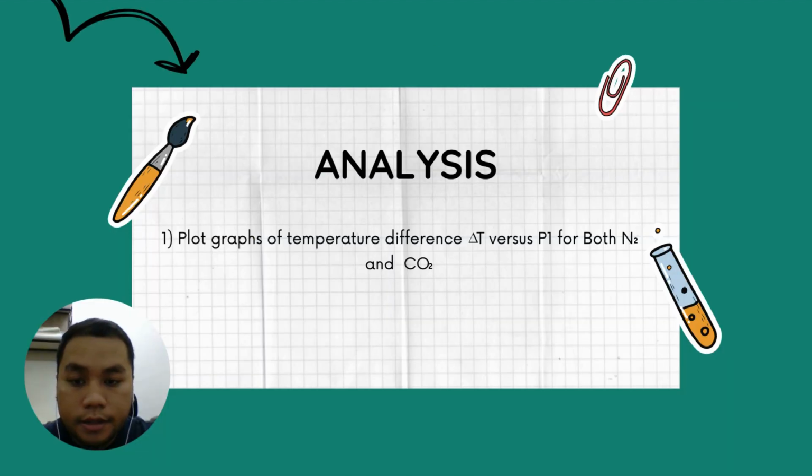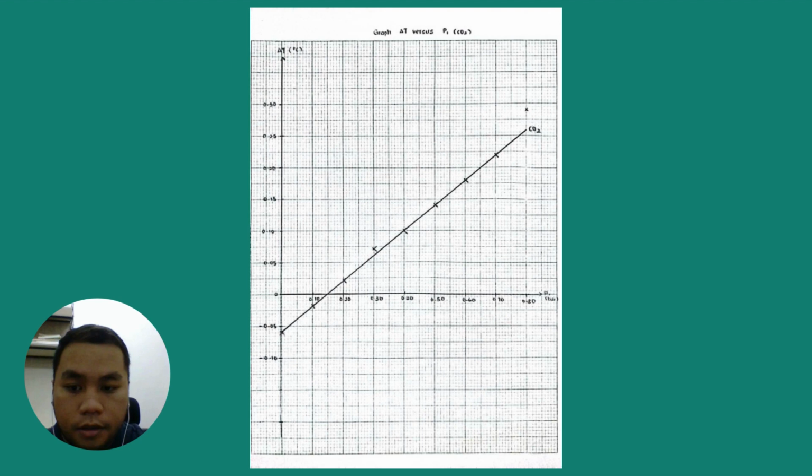The first analysis is to plot the graph of temperature difference versus pressure for both nitrogen and carbon dioxide. So this is the graph for temperature difference versus pressure for carbon dioxide. We can see that the temperature difference is increasing linearly with pressure, and for pressure less than 0.1, the temperature difference is negative.